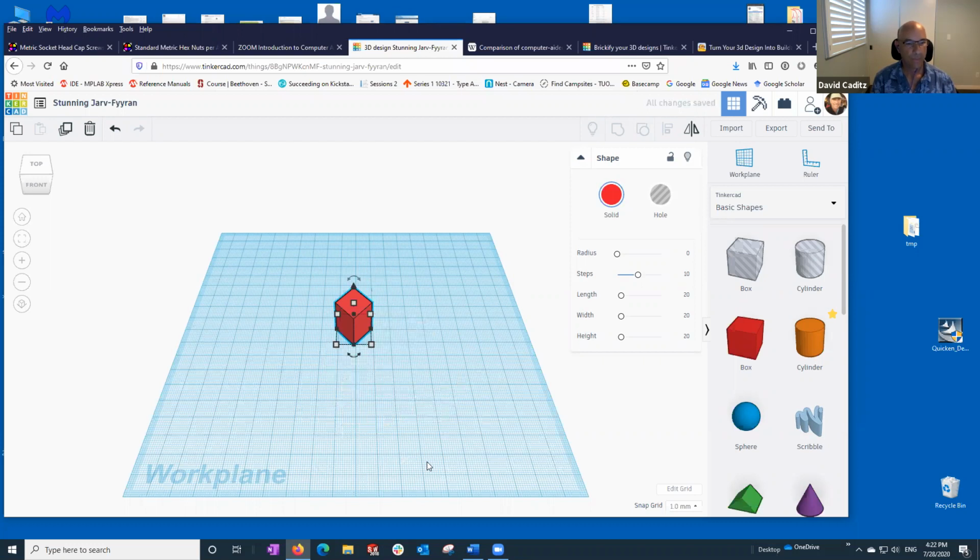The dimensions are always XY dimensions. So because I rotated it 45 degrees, now I'm sort of going corner to corner. But if I go back to 0, I guess I have to go minus 45. And now I can get the sides. So say 20 millimeters and 20.